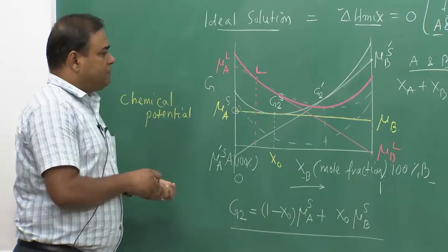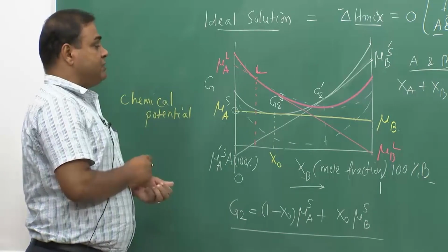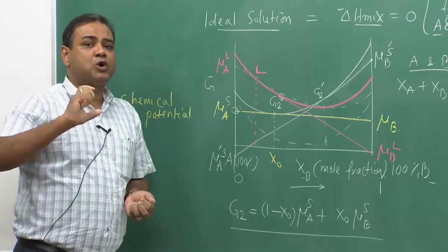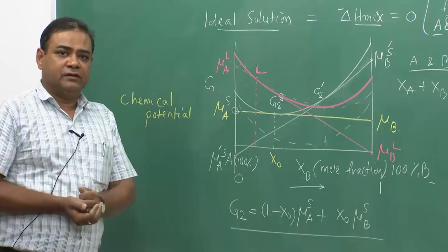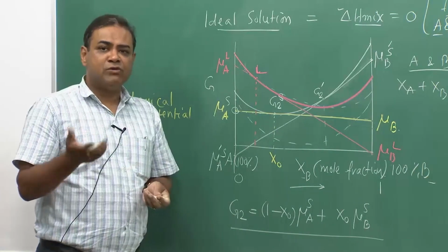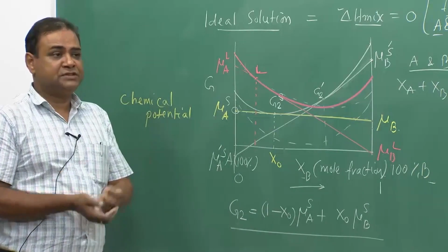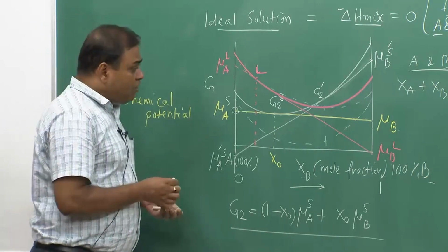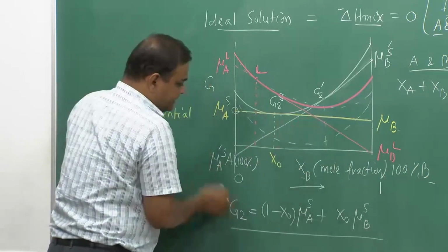Now, just for the sake of understanding, this information would be useful later on when we try to find out the free energy difference for the transformation, when we talk about a transformation from solid to solid, okay? And every time, in order to find the nucleation rate, we need to find the volumetric free energy change, which is actually giving the driving force. So, that will be required.